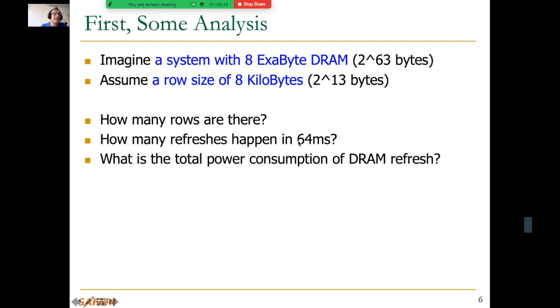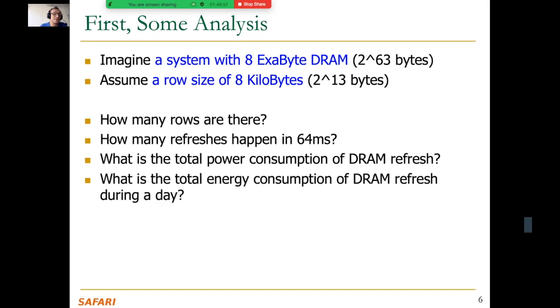But you need to do this calculation by figuring out how much current is drawn by refresh and calculate the power by looking at the parameters of the DRAM chip. And what is the total energy consumption of DRAM refresh during a day? So you can calculate that once you figure out how much power is consumed by DRAM refresh.